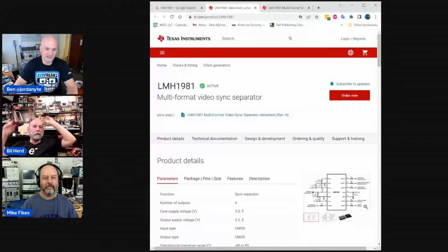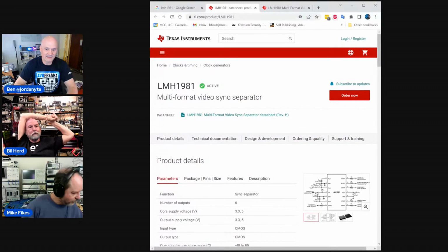There's so many options though. You know, like LT is a good one. There's so many free options. Most of even the commercial Spice tools that are built into ECAD are now based on NGSpice, which is the descendant of Spice 3 from Berkeley that includes mixed signal capabilities. So it has a whole set of extensions that let you do mixed digital and analog, and it's still maintained as open source, and there's a few different front ends on that.